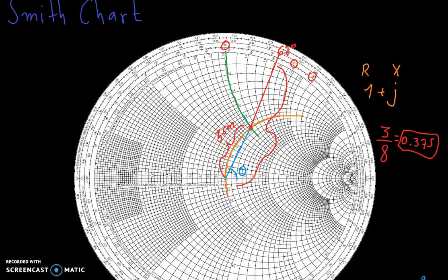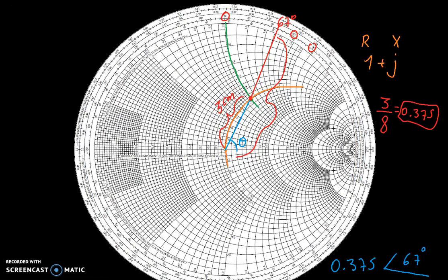So as you can see, it's quite easy to calculate. The Smith chart helps you a lot. And just one more thing about the Smith charts before the next tutorial. You have to realize that this chart here has 2 types of coordinates in it. The reflection coefficient is using polar coordinates, with the center here equaling 0, r equals 0, and this axis here is theta equals 0. And this is the imaginary axis, and this is the real axis here.